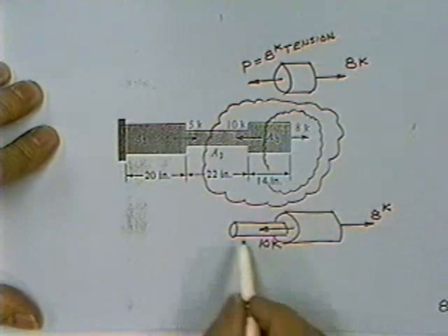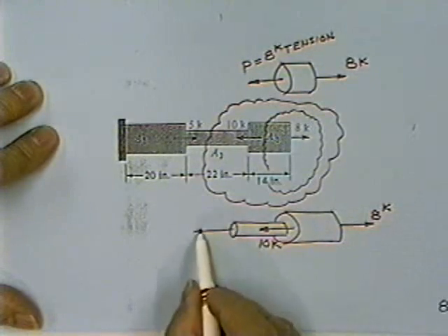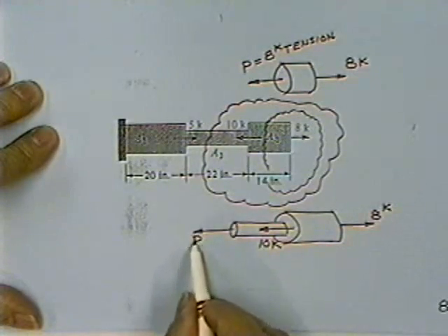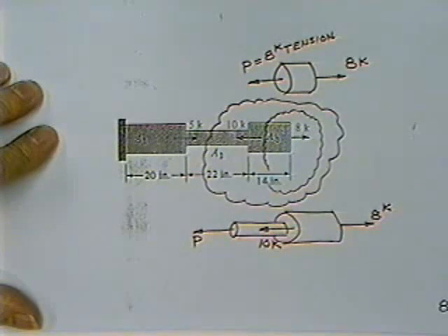Put the unknown force on the free body. Many times, although you might look at that force and say, whoops, that wasn't real smart, you really can't outguess which way that force is going to go. The problem just gets too nasty for you to tell. It's just about as easy to always put the force in tension.